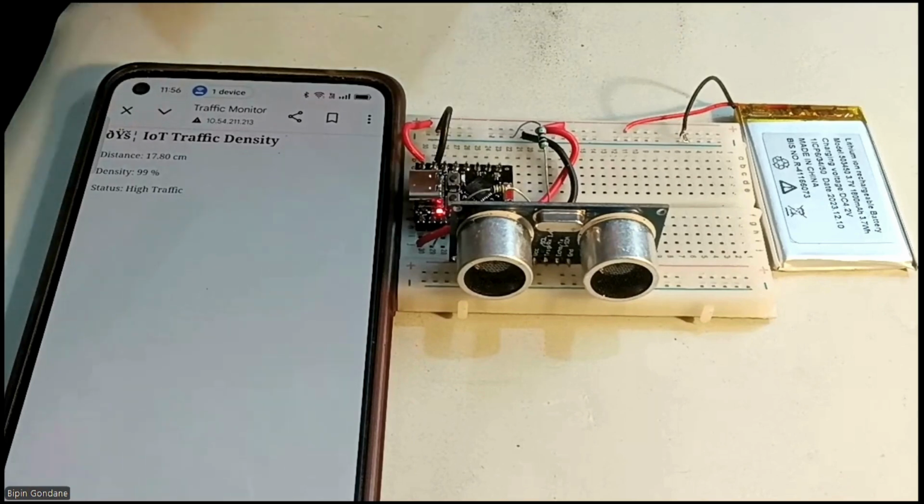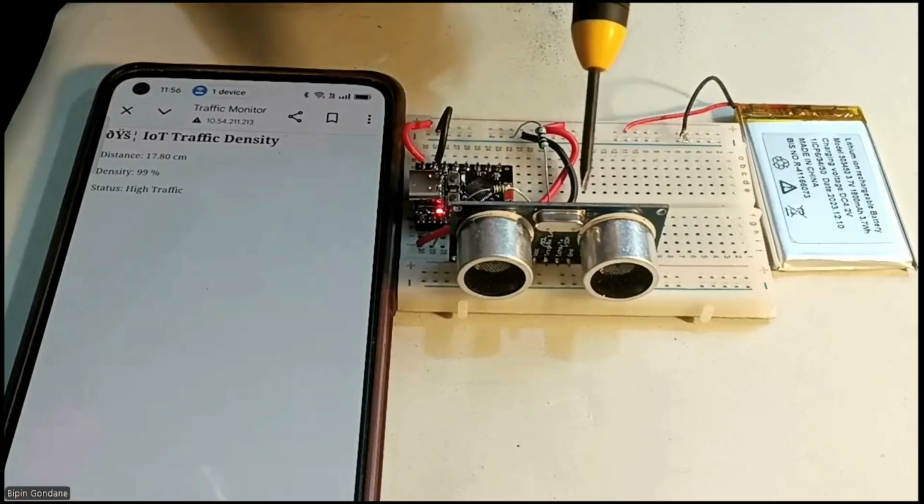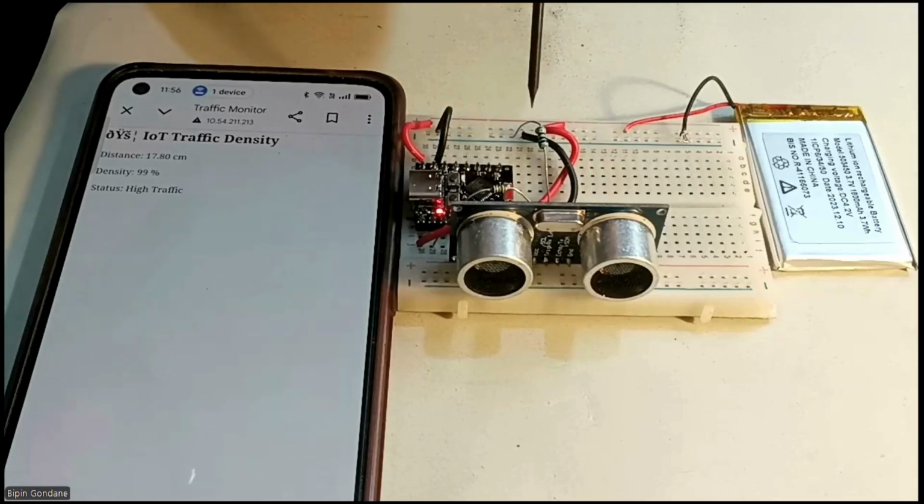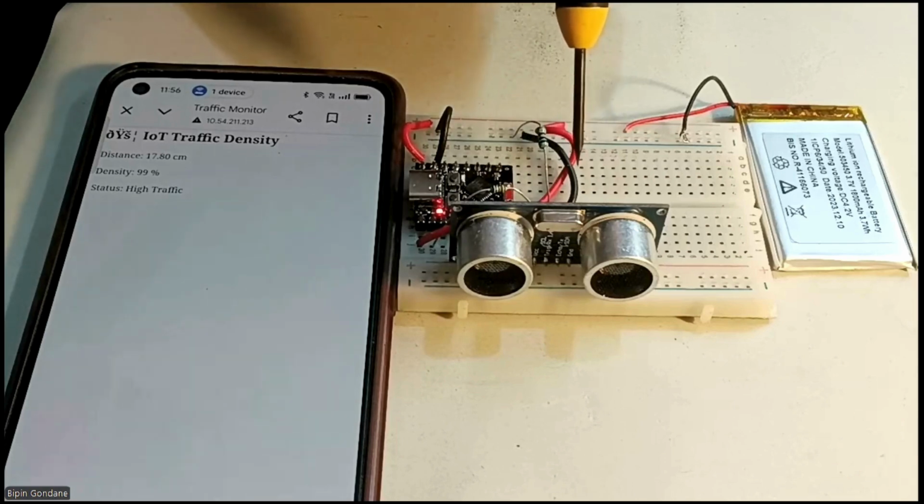Okay, first of all, this is my board. This is a compact board. This is an ultrasonic sensor. We can use two sensors also, two sensors on both sides and two resistors, as I have told you in the circuit diagram, a pull up and pull down resistor from pin number 5 and pin number 6. That is from the echo side. So this is running on 5 volt.